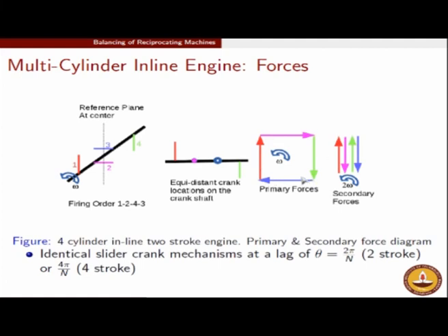And if I do not take the x component, the sum total of the rotating unbalances in this case is 0. So therefore if the sum total is 0, the x component of the rotating unbalance is also 0. So in this fashion I have completely killed the primary unbalanced forces, right. The secondary unbalanced force is even simpler to analyze. In the secondary, this is the primary crank diagram.